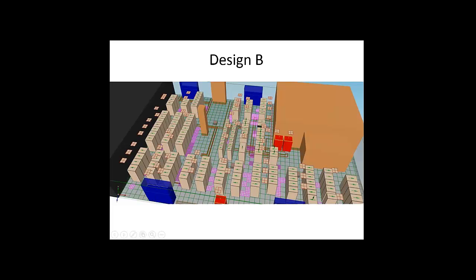Yeah, this is the summary of this data center, and here's a shot of this one. This is a very typical data center I see a lot. It's in a process of evolution. You've got most things in hot and cold aisle configuration, but you can see the ceiling tiles here are certainly misplaced, and you've got some equipment like this one right here where the air is pointing at 90 degrees to everything else. And there's a couple of classroom style here.